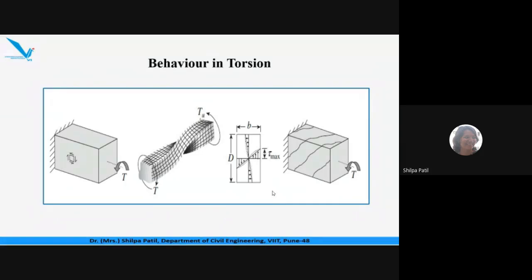So if you recall the design steps for design of beam, let us consider a simple example, design of a rectangular section, which we have to design like a singly reinforced beam. In this, we consider one force, that is the bending moment, separately. And to resist that bending moment, we provide the tension steel in the tension zone. Okay. And then the second force is shear force, in which to resist that shear forces, we provide the stirrups, which are along the face of the member. Okay. So by providing tension steel and stirrups, we are actually considering the resistance shown by the member to the bending moment as well as shear force.